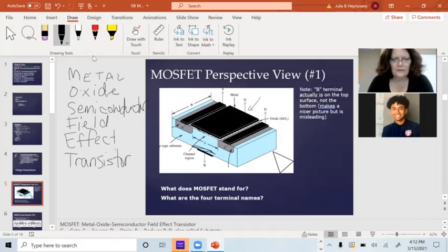Now, I'm getting way ahead. The way this thing is usually biased: this is an NMOS. The body's grounded. The source may be grounded. This is a typical setup. The drain's going to some positive DC voltage. I'll just talk about those 3 terminals first.